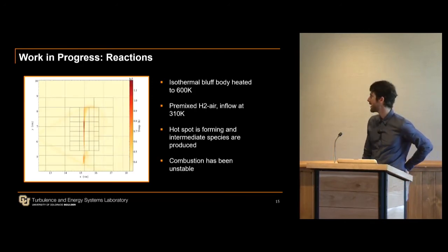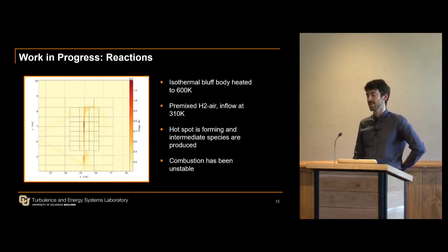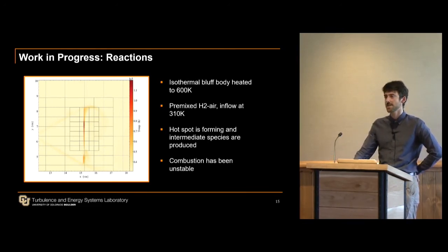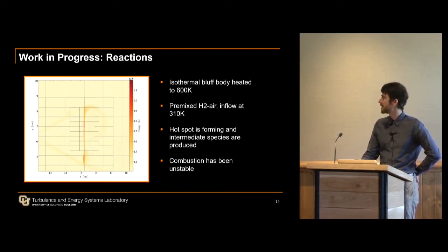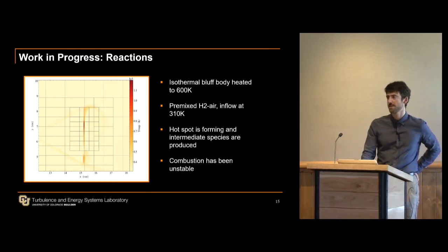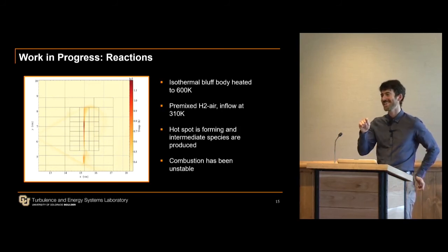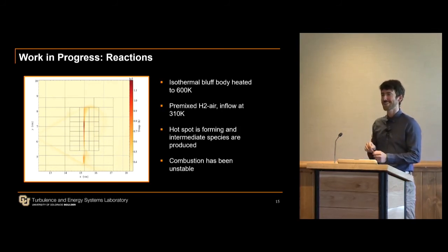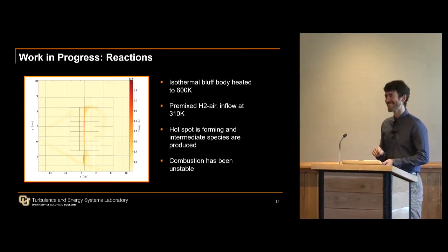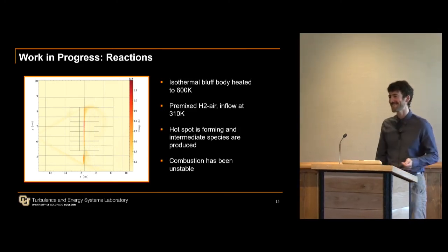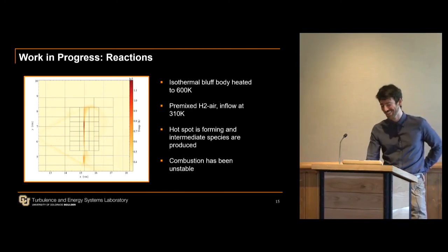So I mentioned that we're working on getting combustion going. This is a little bit more of a challenge with the AMR codes than it is for static refinement. Currently, we're seeing some numerical instabilities at the boundaries of the AMR grids as the combustion propagates through them. So that's what we're working on currently. And I've been checking right up until about half an hour before this talk. I think I have a stable simulation going, so maybe if you had me give the talk tomorrow, I would have had full results for you. That's a little unfortunate, but I am excited that it's finally seeming to work.